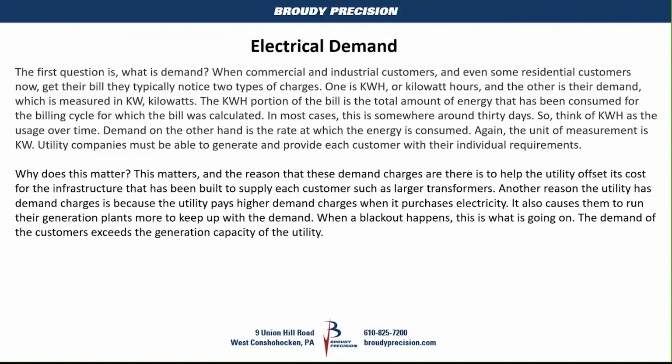These equations that I talked about in the beginning come into play. So the first customer in the example would require a larger transformer based on the calculations that I just threw out there. His demand would be 1 kilowatt, right? So the demand for the second customer would be 0.01 kilowatts. I'm sorry, 0.1 kilowatts. We convert this to amps, right? We showed that equation earlier. So amps equals watts divided by volts.